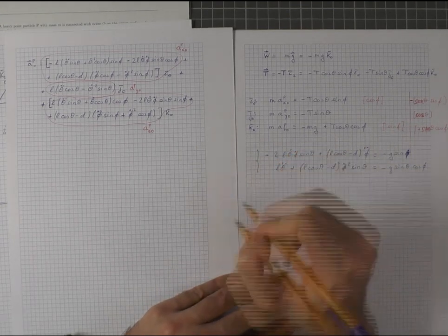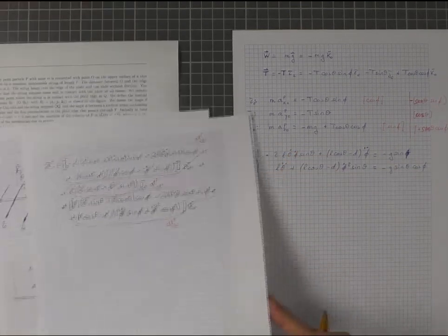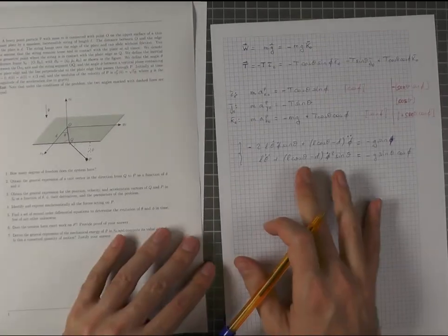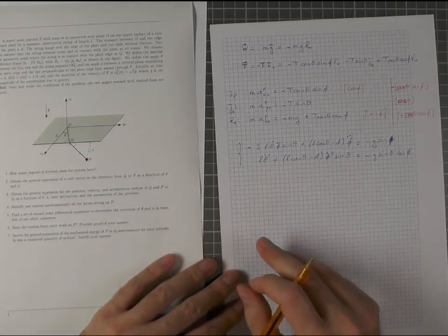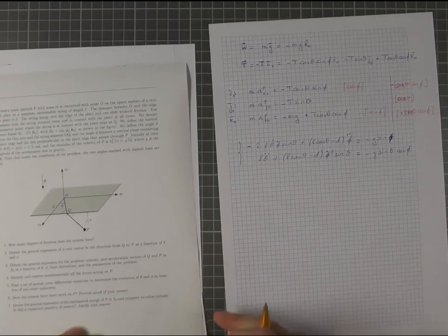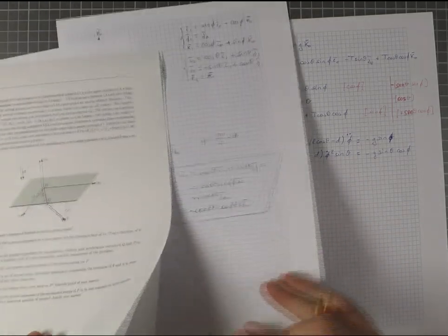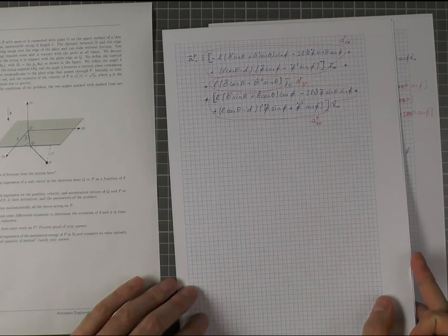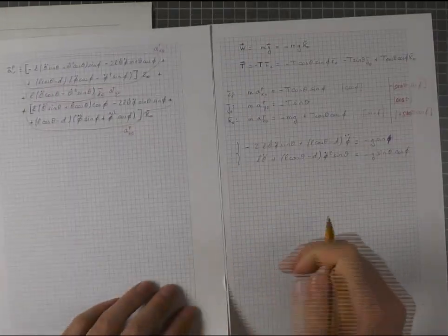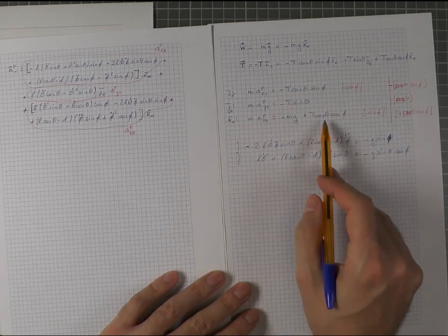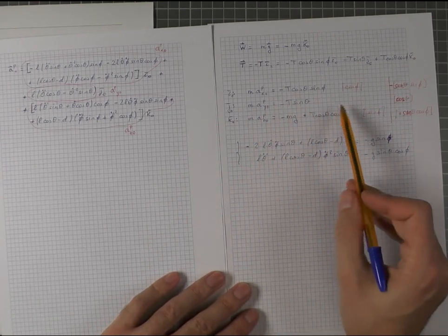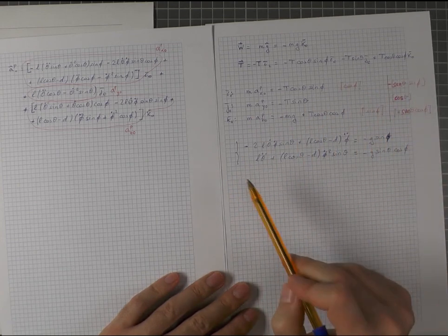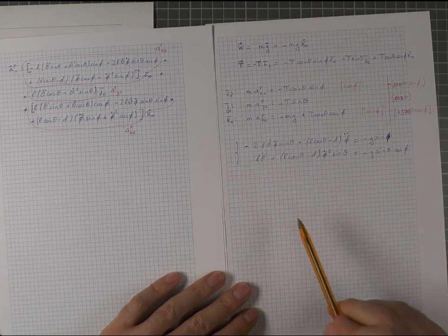So these are the two equations that the statement of the problem asks us to find. Okay, so I will say it again. What we have done here is a little bit more cumbersome. We have worked in basis 0, so we have obtained pretty long expressions for the acceleration of the point particle P in this basis. And after writing down the equations of motion in this basis, we needed to find two linear combinations, multiplying by these factors and adding together, that yield expressions that don't depend on t.